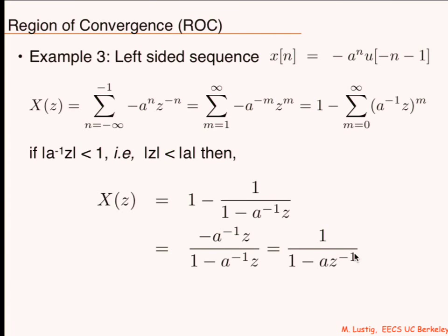So what's the solution to get rid of this ambiguity? Every time you show me a z-transform, if I want to know the actual sequence that it represents, you have to tell me what the region of convergence is. Otherwise, it is ambiguous. So they have to come together.